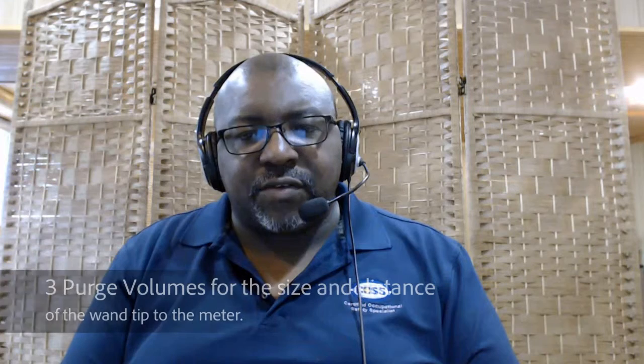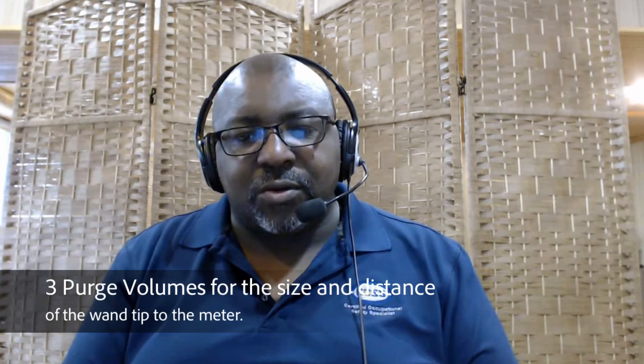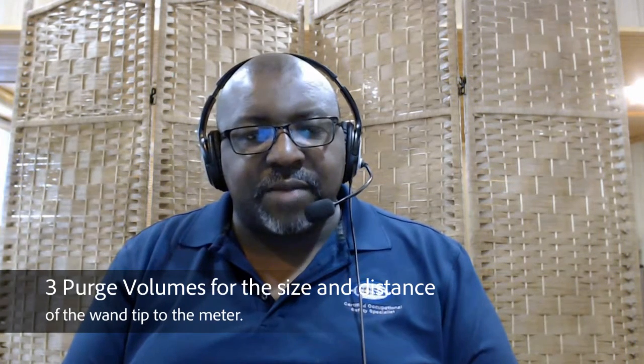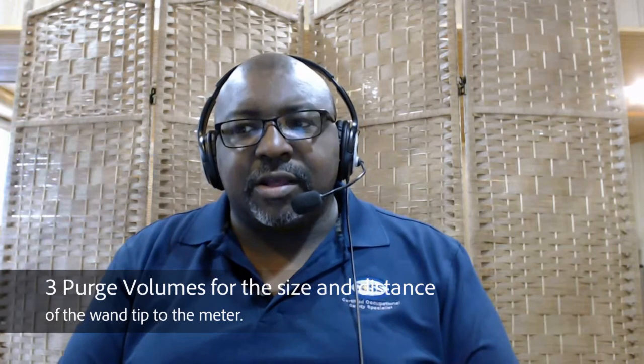Your meter's pump is going to be pumping through that gas and giving you enough time to do 3 purge volumes of that actual hose. So that's a function of math, where basically you're going to go for pi r squared times d, so pi, 3.14, times the radius of that tube squared.